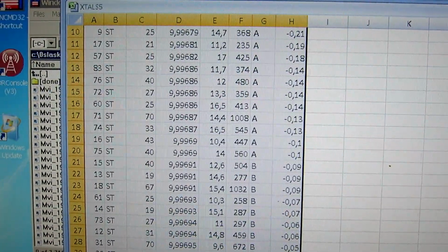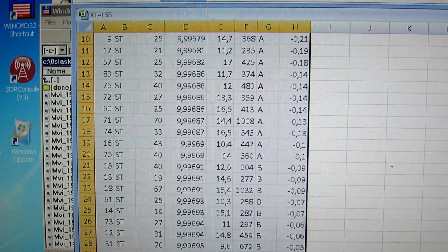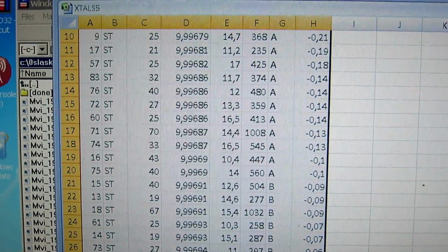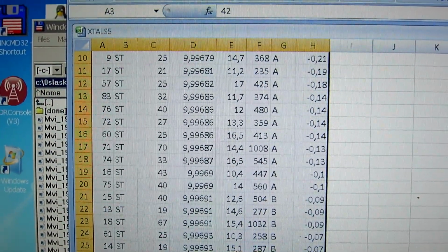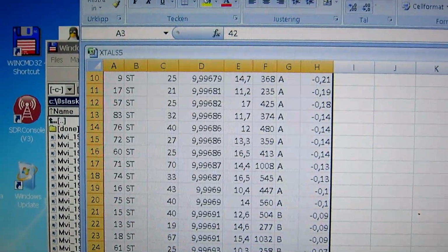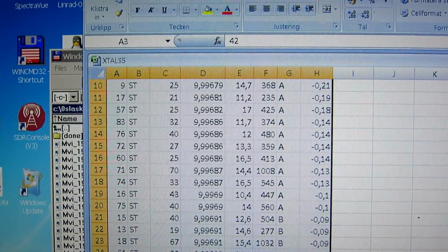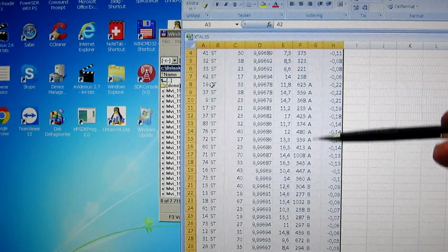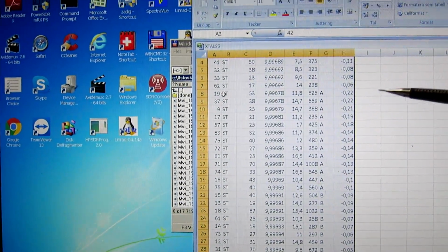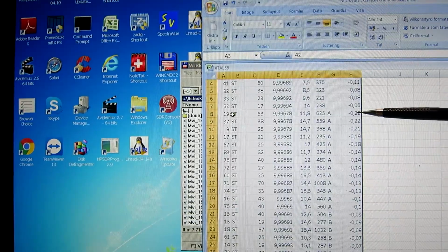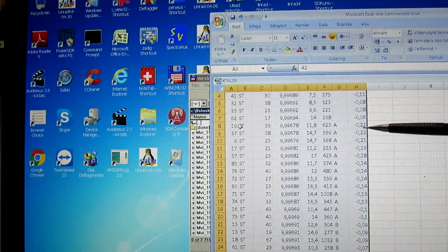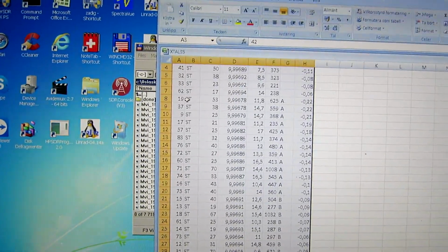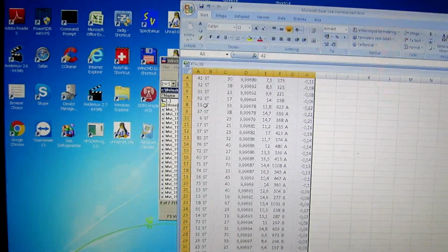These are the two groups of 13 crystals, A and B, that I have selected to use for the two notches that have 1 watt of power, or rather the current associated with 1 watt of power. The frequencies of the crystals within one group, say this one, differ. This is the frequency separation from some reference. It is 220 Hertz down to 100 Hertz. So it's a frequency difference of about 120 Hertz.